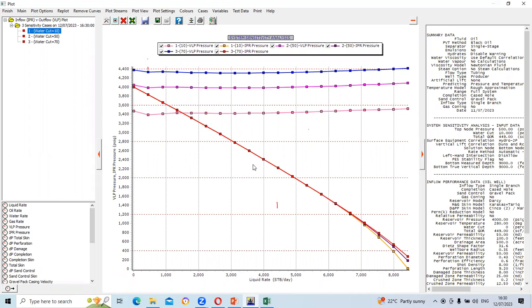So if you look at the nodal analysis, your essence is to identify where the problem is coming from. The well is not flowing. Is it that the reservoir is not performing, or the well bore itself is not performing? If the reservoir is not performing, we could definitely bring something like water flooding to see how to push the oil. Maybe the reservoir pressure must have died down and there is no sufficient pressure to push the hydrocarbon.